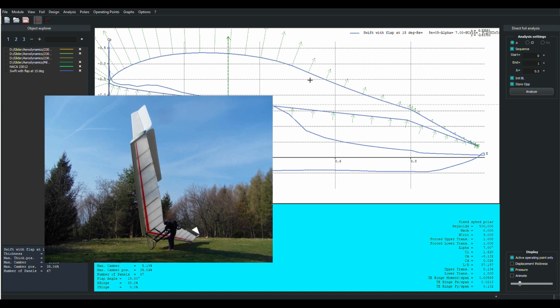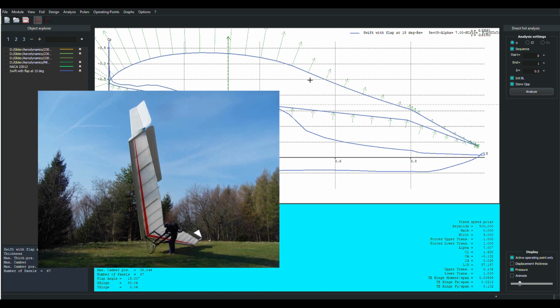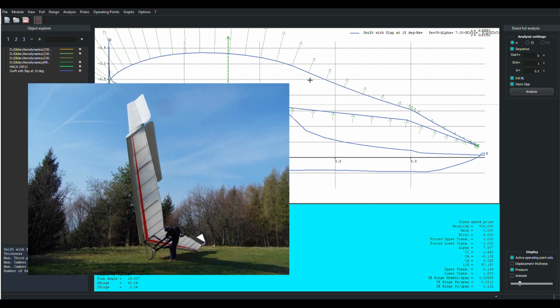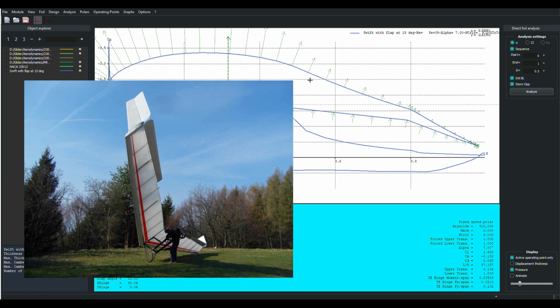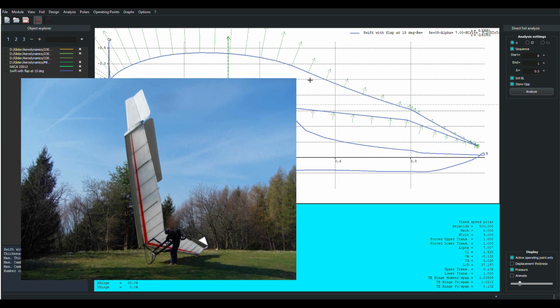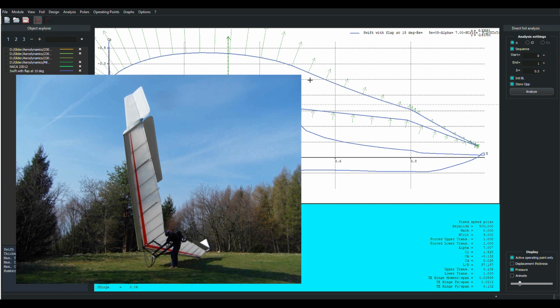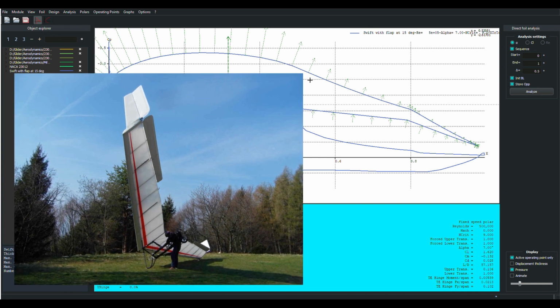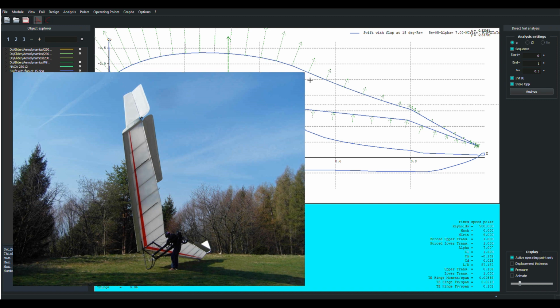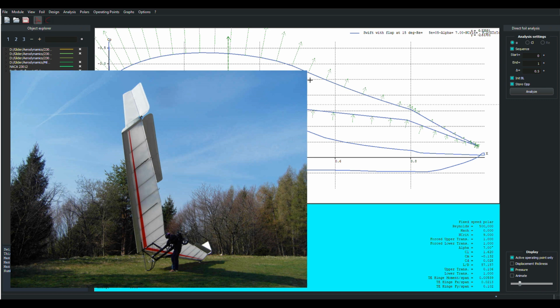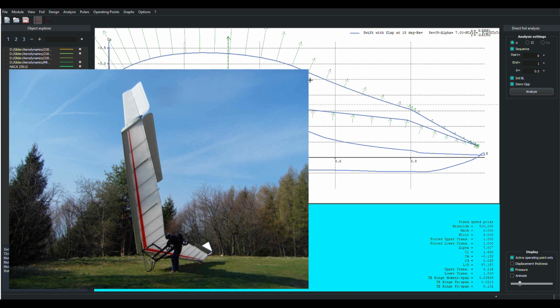And he pinched his ribs, brought them together in a pattern where they got effectively thicker airfoil as you get out towards the tip, because he's pinching the ribs together, and he's tacking an elevon onto the trailing edge just like the rest of it because it's easy for transportation. And he ended up with this reverse taper elevon. And I sent him a message once and I asked him why he did it. He did not do it in terms of the stall spin problem, hadn't thought about that.